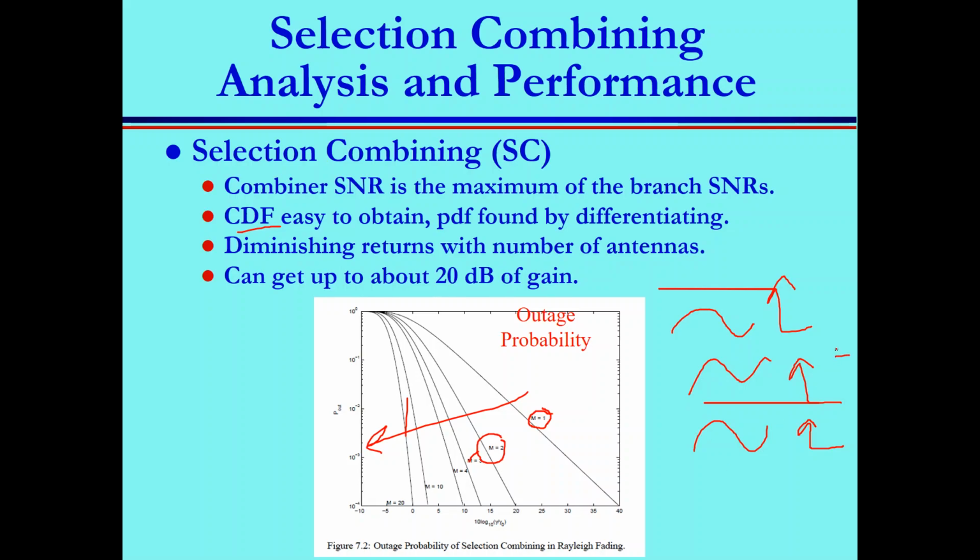Now, you sum them up using maximum ratio combining: you co-phase them, and you sum them. Now, I need to analyze the performance. In the analysis of the outage probability, what should I do? I must find the probability distribution of the SNR. The distribution of the instantaneous SNR is controlled by the distribution of the instantaneous fading you have.